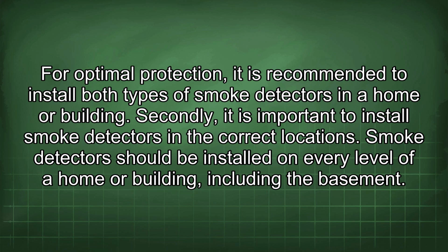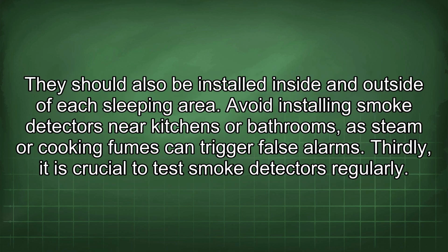Secondly, it is important to install smoke detectors in the correct locations. Smoke detectors should be installed on every level of a home or building, including the basement. They should also be installed inside and outside of each sleeping area. Avoid installing smoke detectors near kitchens or bathrooms, as steam or cooking fumes can trigger false alarms.